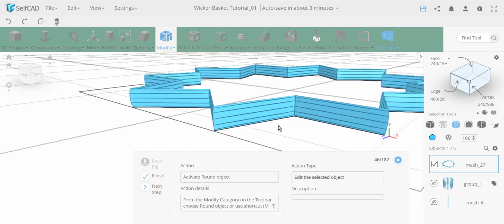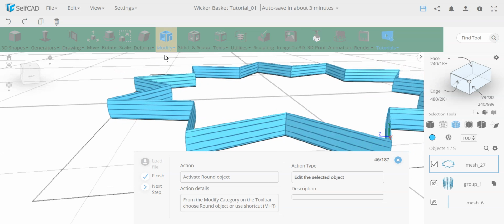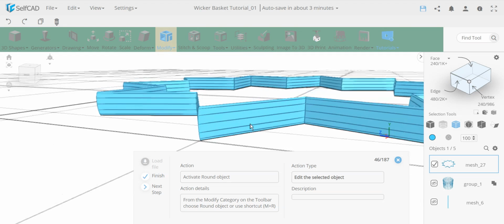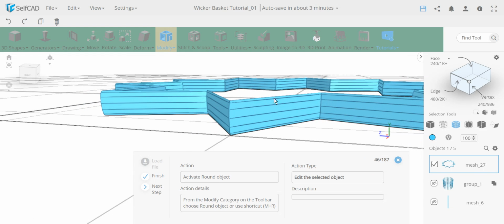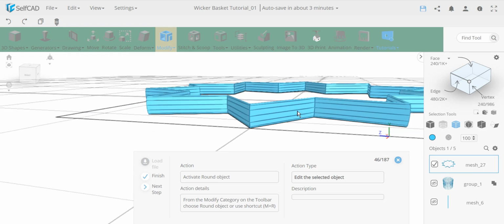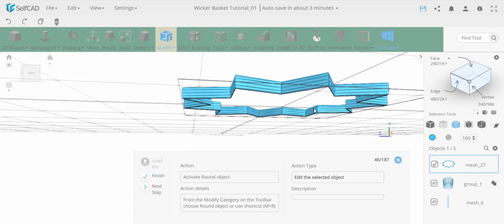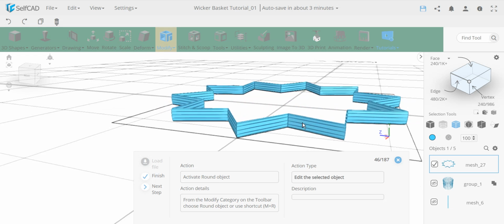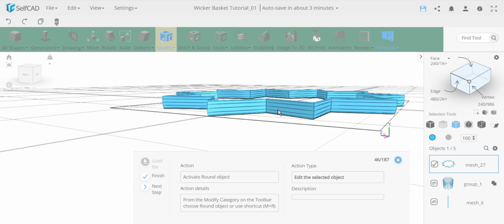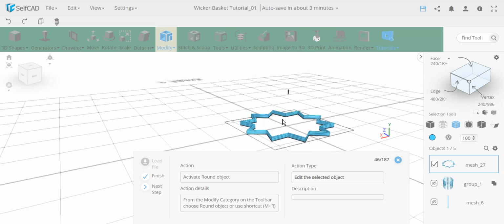Now you could have actually done this using simple extrusion to get a height. The only thing is that you have this curvature. You see, this is not flat. If this were 100% flat, simple straight up, this would work, and this would basically be a 2D shape converted into 3D, simply extruded. But in this case, this has some curvature, it's not flat, and this is why we needed to use a different method to do this.